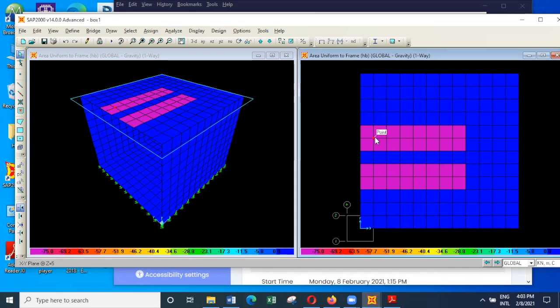I have considered that this acts here, at the center line, and then the centroid should be 1, 2, 3, 4, somewhere here. But if I consider the actual loads at 1.8 meter, if I consider that the center is here, then it's too far. Because of that reason, I have considered that it acts at 1.5 meter.